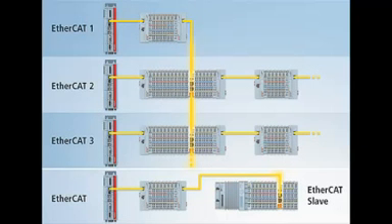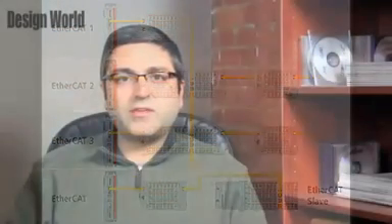It can work with UDP in a protocol stack, although it won't be deterministic. Also, switches and routers between the master and the slaves will negate determinism. Lastly, this protocol is compatible with SERCOS. The next network is EtherNet/IP.